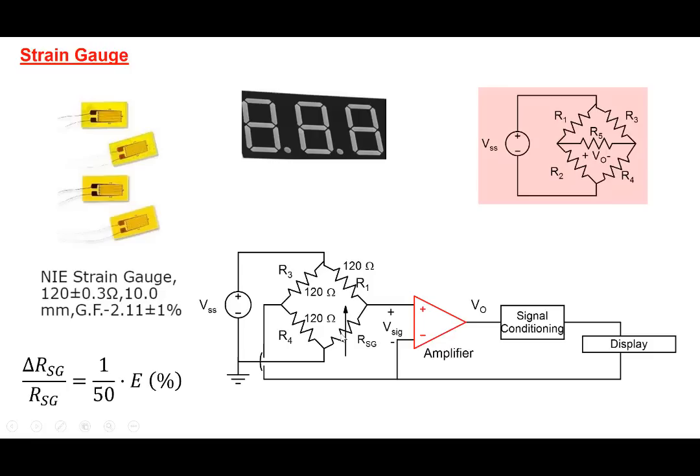As part of this, we have a Wheatstone bridge here. In general, because we are applying strain, and also because resistors, even if you choose them 120 ohms and 120 ohms, will be a bit different from 120 ohms, and temperature also causes a change in the values of the resistors, these resistors R1, R2, R3, R4 will not be the same. Our interest is in finding the voltage across R5, because this is the voltage that goes to the amplifier and is eventually displayed on the screen. So we need to analyze this Wheatstone bridge in the general case, where we have all these 5 resistors.